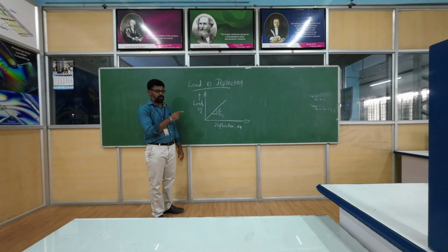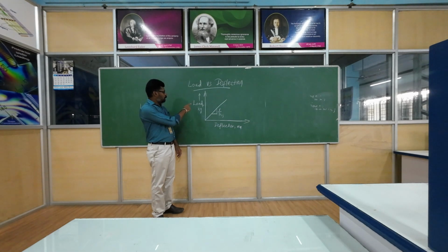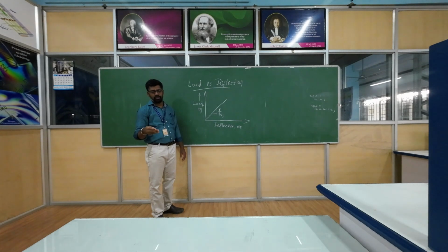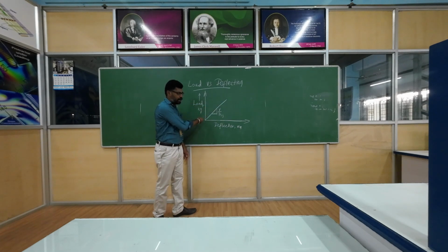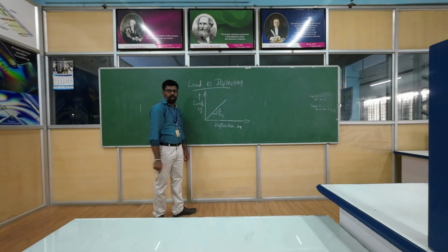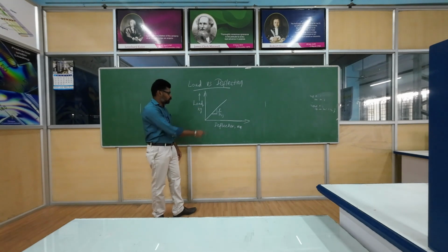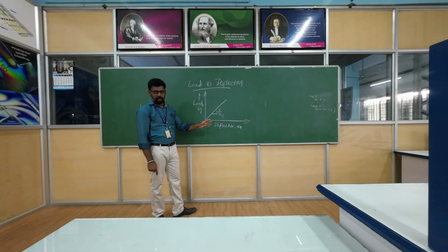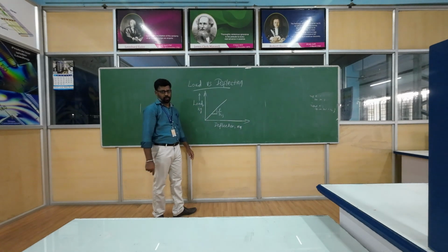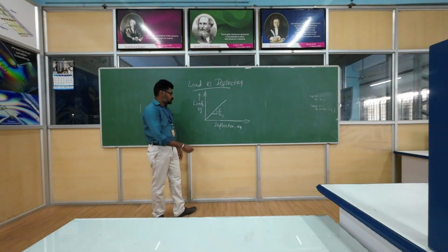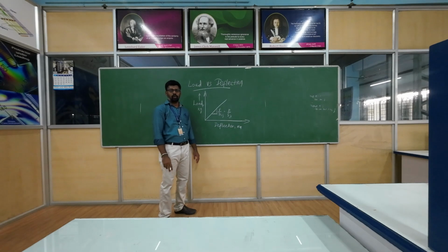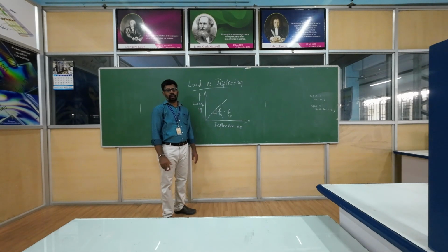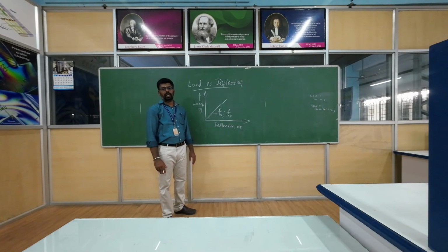Now we are also going to prove Maxwell's reciprocal theorem by plotting the graph between load and deflection. Here we already have the load values of five different readings and the corresponding deflection values. Just plot the load value against the deflection value and you will get a linear curve. This curve gives the slope for case 1, that is P by delta ij. Similarly, we can plot the load versus deflection curve for case 2 and get P by delta ji. Both slopes would be equal. So by plotting the load versus deflection curve, it is possible to verify Maxwell's reciprocal theorem.